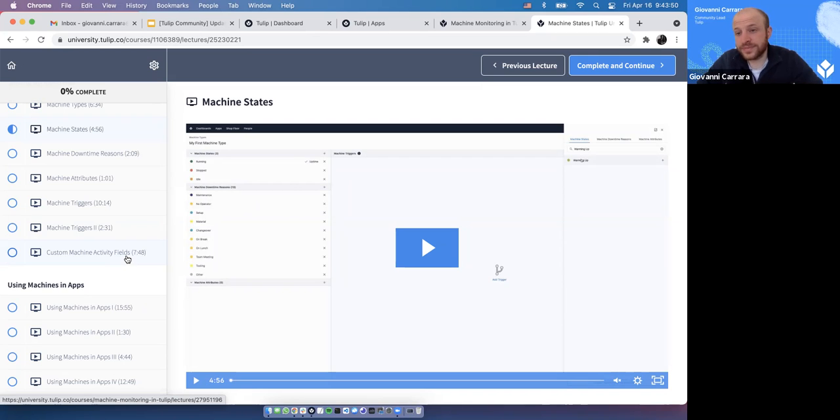It's an interesting one, and it sounds quite simple. It's just a matter of getting data from Kepware into Tulip, and then within Tulip, it's quite easy to process the data and display it for the operators, so that when they come into the new shift, they know when it's time to change the tool. They change the tool, press a button, and it resets the counter, and then away they go. When it reaches 90% again, it starts flashing red at them again.